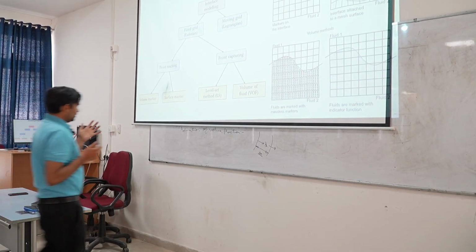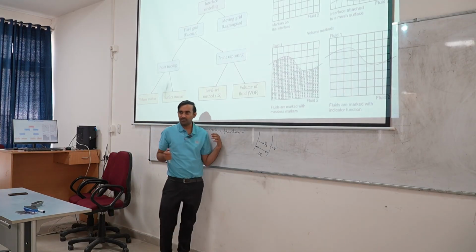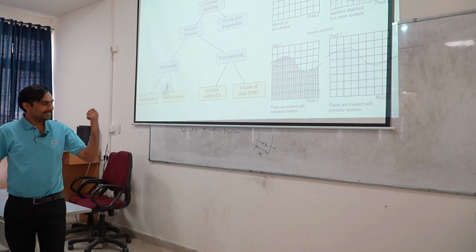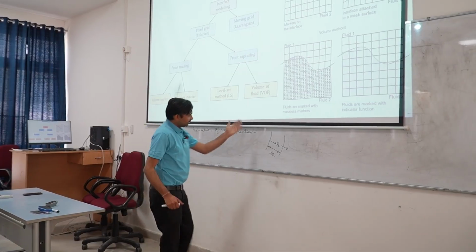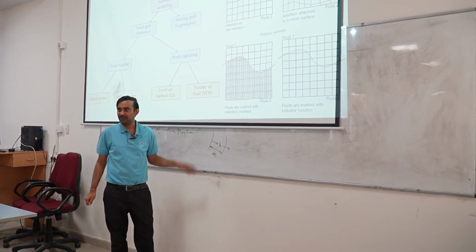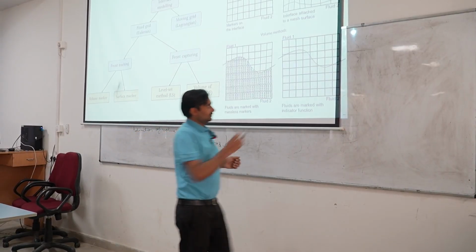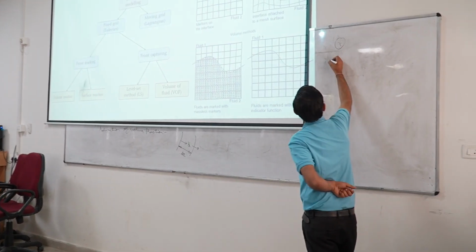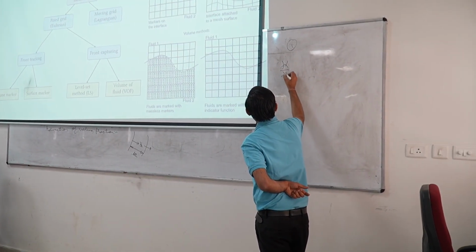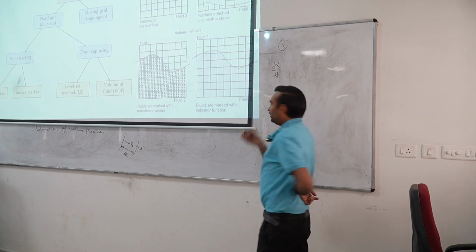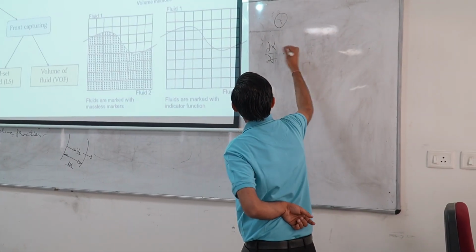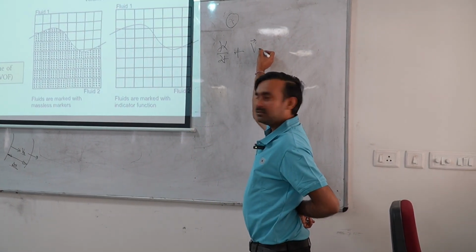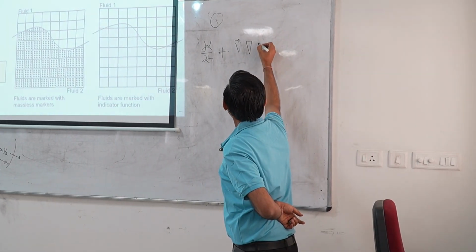So, it means that we have to develop some mathematical equation which can first calculate the velocity normal to the interface, and after that can advect the volume fraction field with that velocity. If I define my volume fraction with the parameter alpha, I can say that the rate of change of alpha with time will be dependent upon the velocity field into the gradient of alpha.